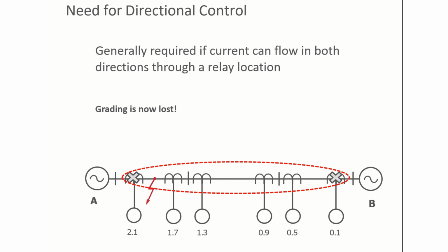Yes, the current is definitely going to change, and we are not talking about how to determine this direction, because direction determination in an AC system depends upon some reference quantities known as polarization quantity, and we will see in the upcoming sessions how to determine the direction.